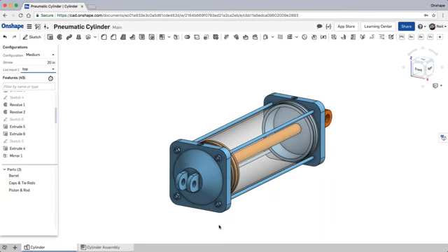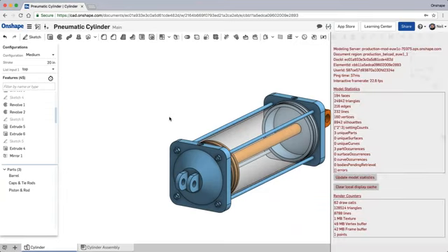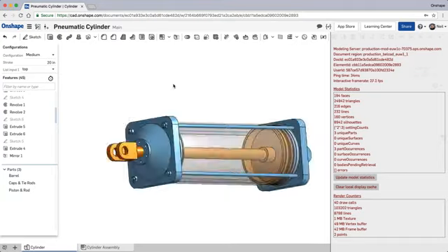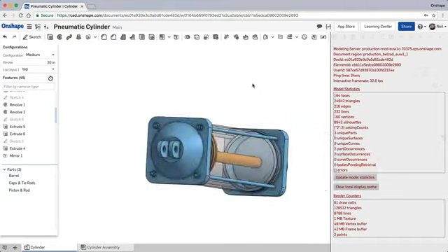I can't put a figure on it, to be honest, but anything less than 100 milliseconds latency is absolutely fine. I think if you press Control D inside the Onshape browser, you can see exactly what you've got here. So I'm running at a ping time of 39 milliseconds, and I'm getting a frame rate of 30 plus frames per second in here.